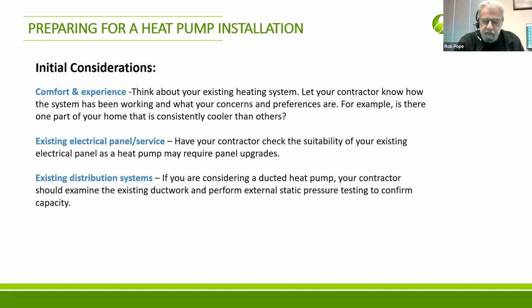First of all, the HRV is running continuously. It can be bumped up in speed for sure when there's a humidity gain or for other reasons. If you have a reasonably good filter rating or better, and one of the things that we like to do is put a UV light into the plenum, all these things combined tend to provide indoor air quality that does not exceed the CO2 levels. But it's good to monitor it, and that is an option. You can actually have that HRV operate based on CO2 levels.